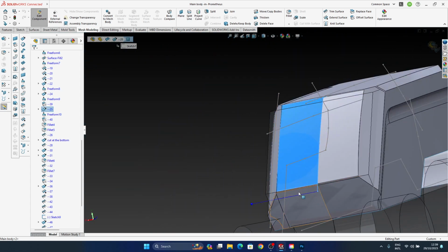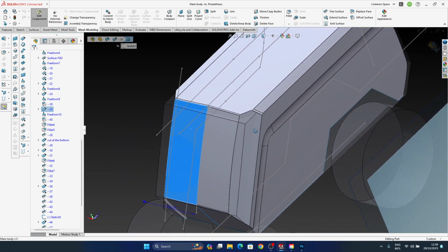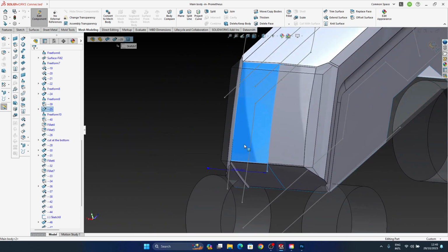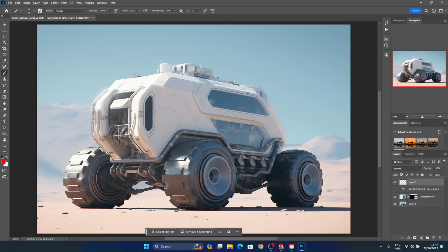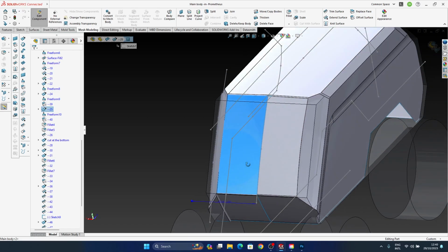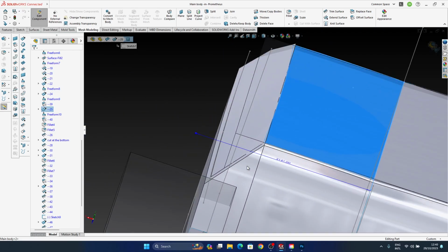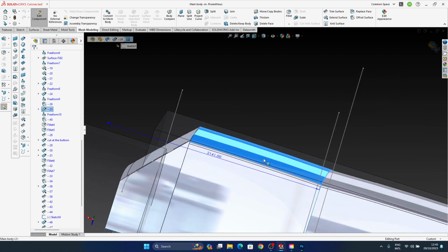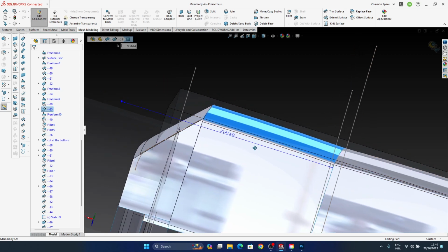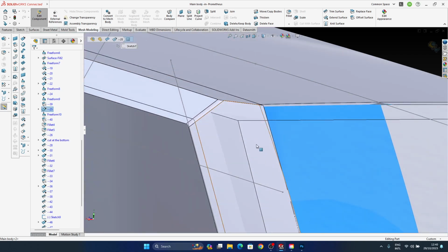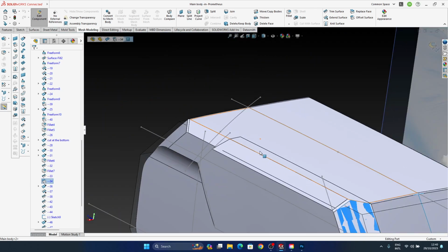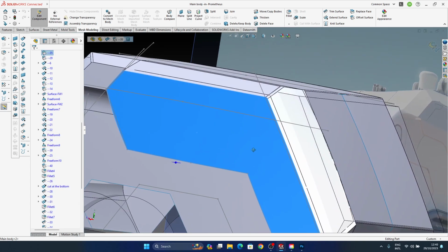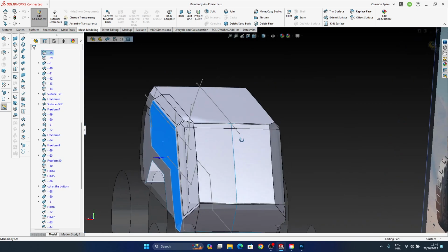But in this situation, we can do two things, especially as the design is not really defined at the back. It can have any shape we want at the back. At the end of the day, it's up to us. So here we can choose to make an offset of this surface in here, which for now is not in continuity with its symmetry, offset this differently, use it as an input for our feature and create a step right there at the back.